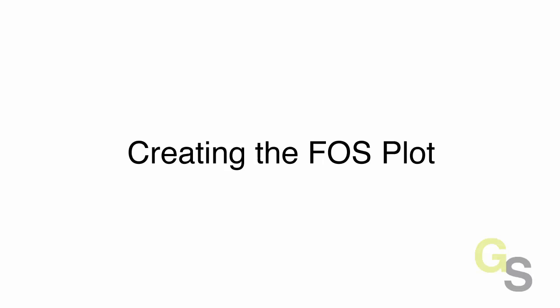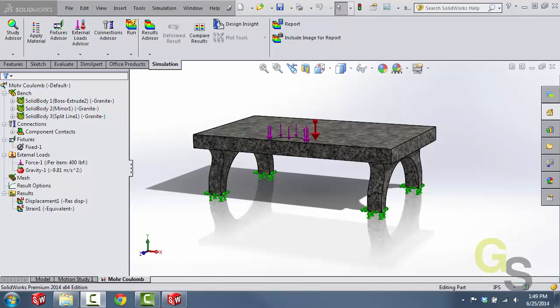At this stage, if we were working with a ductile material or any other failure criterion other than the Mohr Coulomb stress, what we would do is create a stress plot, and then we would be able to compare the stress seen in the stress plot to the maximum yield point, or the ultimate tensile strength, or the breaking point, or whatever it happened to be. But because Mohr Coulomb theory treats tension differently than it does compression, there is actually no stress plot that we can look at that would make sense to us.